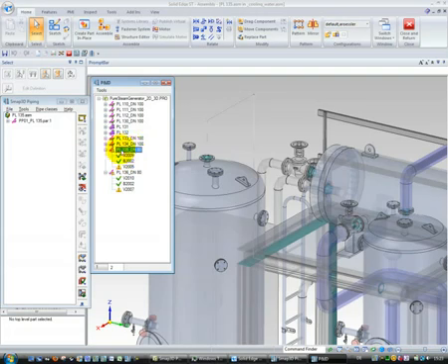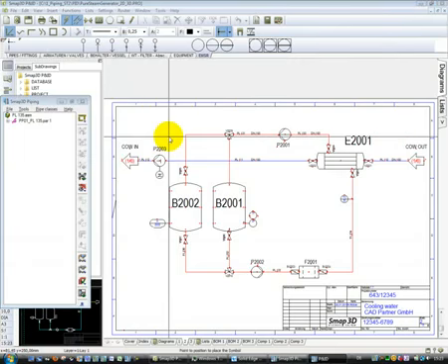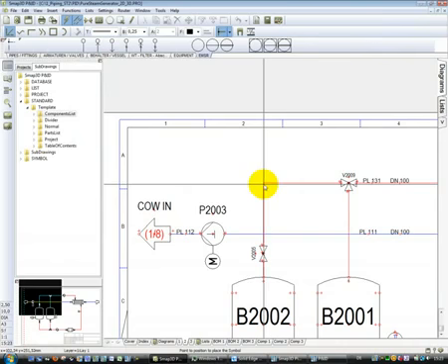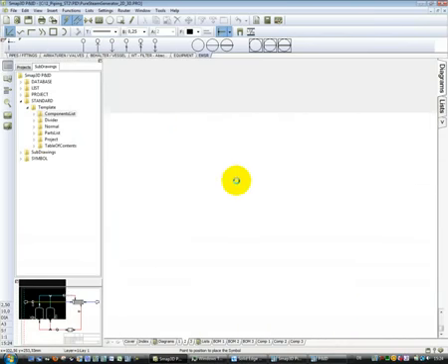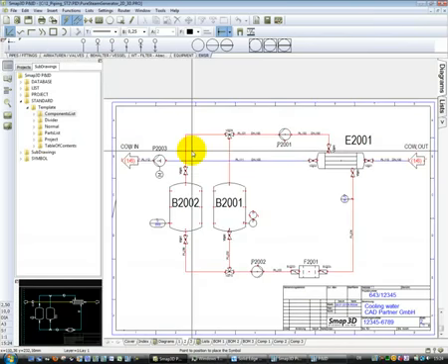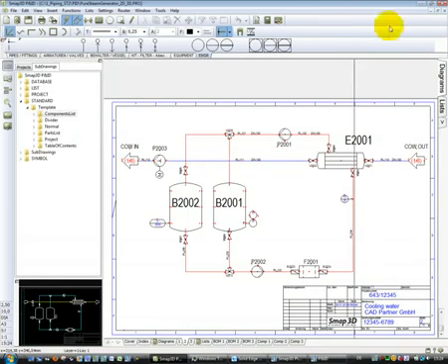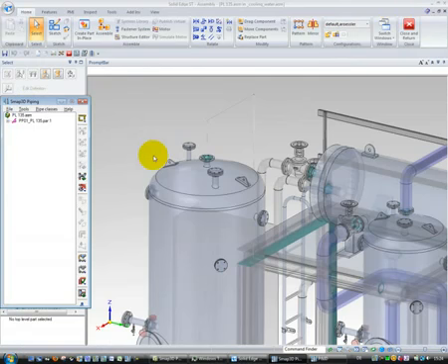In this mask we see that there is a pipeline number 135 and the diameter of DN80. But there is additional information available that we can transport from the Pmid level to the 3D level. So let's take a look into the Pmid. Here we can see that to this line there is also information about the pipe spec which should be used, and additional information. We will see in a few seconds that we can transport this information also to 3D to work further with it.